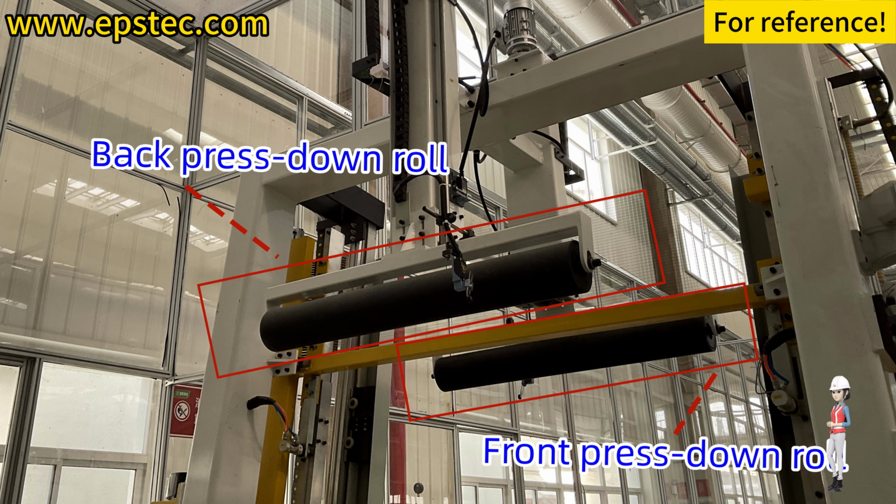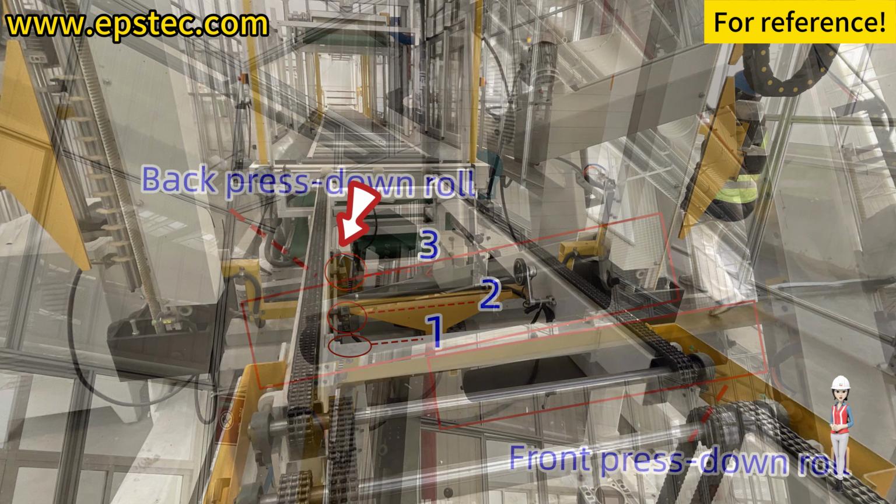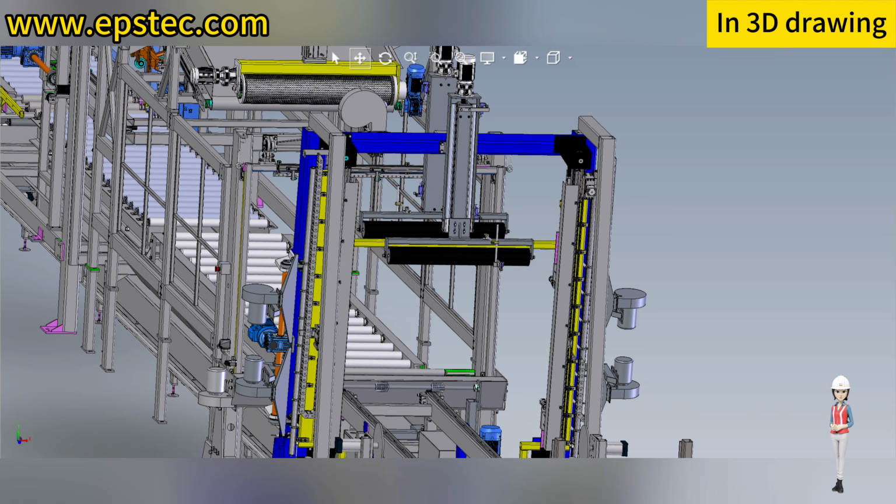And when the back press-down roller reaches the correct position, the front press-down roller moves upwards. When the tail of the EPS block leaves the position of the third photoelectric sensor, the back press-down roller moves upwards. The process repeats for the next EPS block.